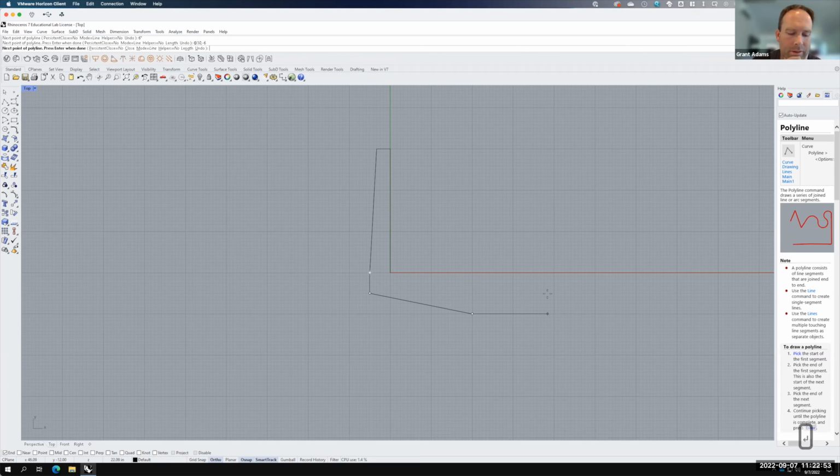I'm going to go back up. So I'll say at, this would be 30 again, comma, +6, because we're going up, and then enter. And then we'll draw up by 6 inches. And then another at, here we go, at, this is -2, comma, 36. Oops, not 367, how about 36? There we go. Enter. We'll go over by 4 inches. Click. We're going to go down by 36, or I can snap, because it should be in line here. And we'll come across, and we're going to end right there.